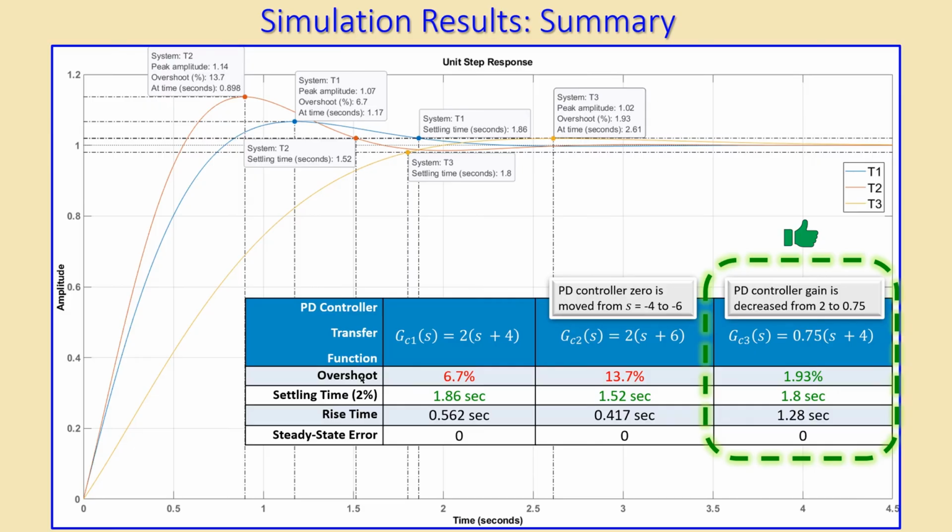So this is now done for this PD controller design. Again, as you can see, our initial design PD controller might not be the best solution. We need to always check that by simulating our controller in, for example, MATLAB, and then tune the controller, of course, using your motivation for why you do that. If you want to shift your 0, you need to have a motivation for that one, also for the gain and also for other parameters.